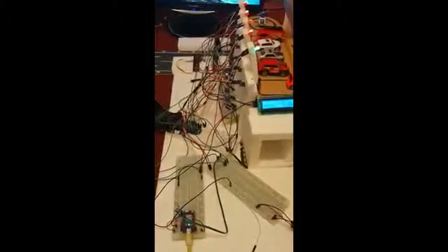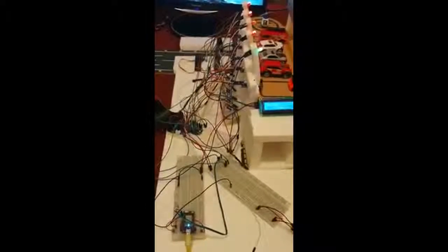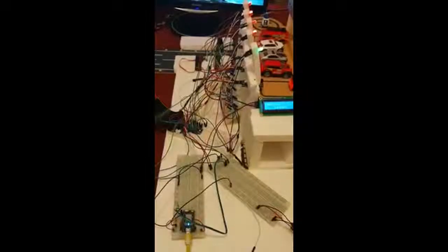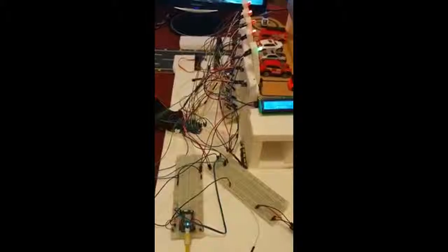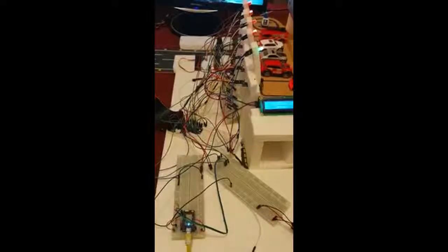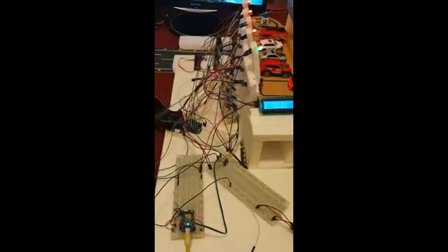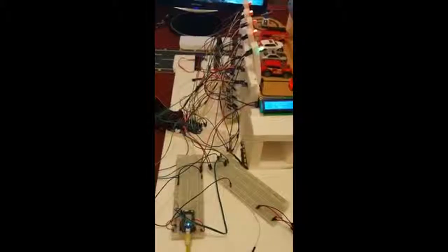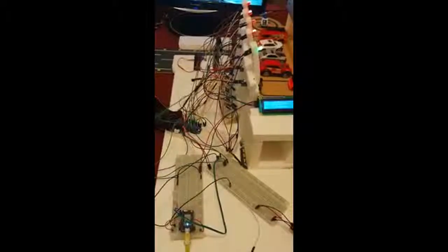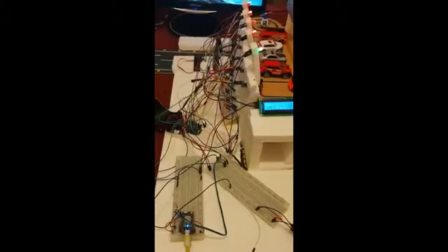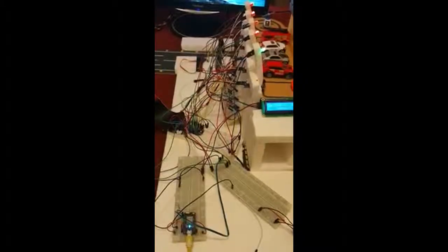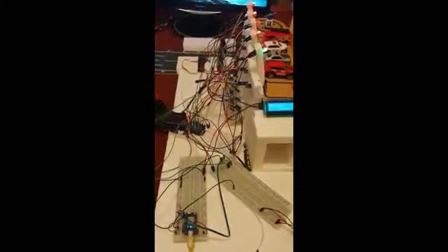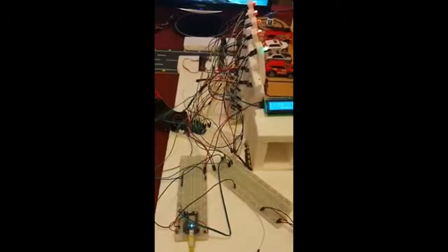As you can see, the LCD screen and the Particle Photon are using I2C. Each one has its own address. The green wire from the LCD and the green wire from the Particle Photon are connected to a green wire to the Raspberry Pi for the data, and the blue wire from the LCD is connected to the blue wire from the Particle Photon for the clock, and the ground is also connected.